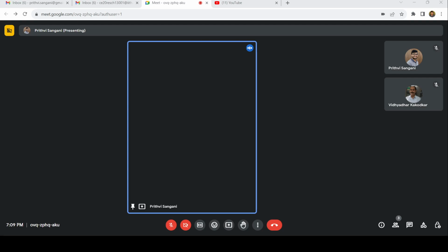So what is going to happen in DC? In DC, I'll take 32.3. So FDC, let me write it. FDC square root of 2 should be equal to 32.3, but this should be in compression, right? So this should be in compression. So 32.3 square root of 2. So that is 45.69. So 45.69 in compression. Okay. So this I have solved for you.